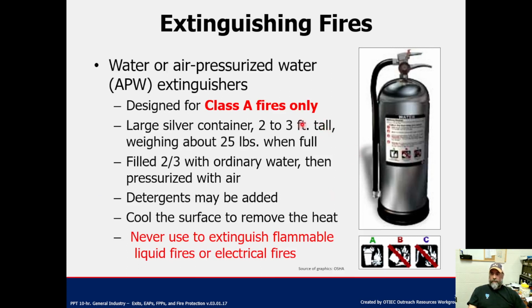Class A fire extinguishers, water or air pressurized water. So if you go back and look at what those Class A fires are, you're never going to be using them on a liquid fire or an electrical fire. So if we see here, it's common combustibles. You don't want to be using those. Definitely don't want to be spraying water on an electrical fire.